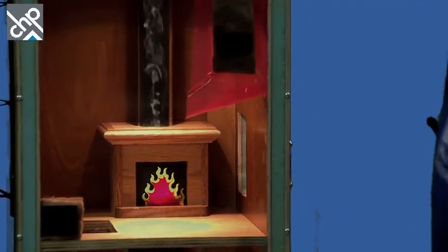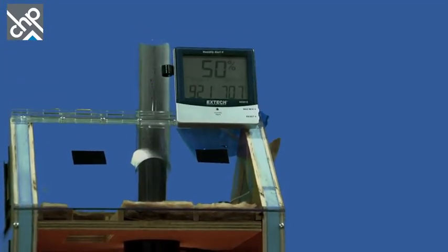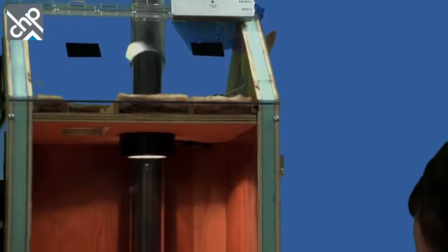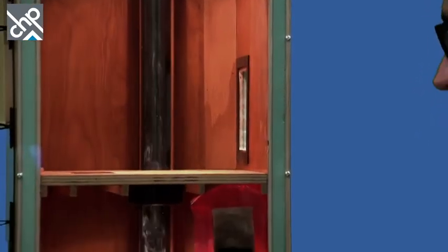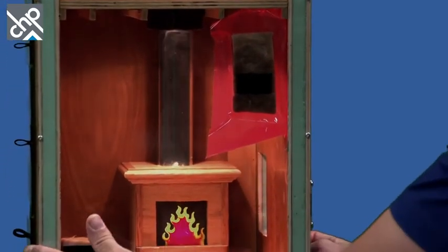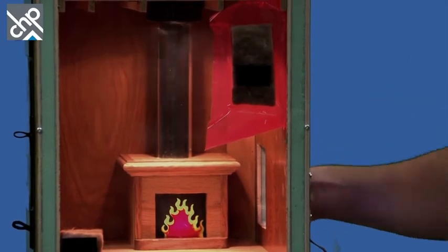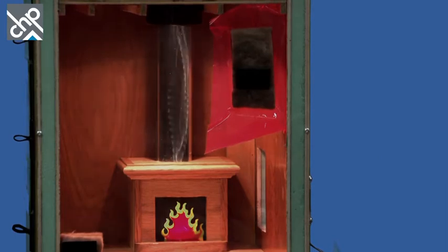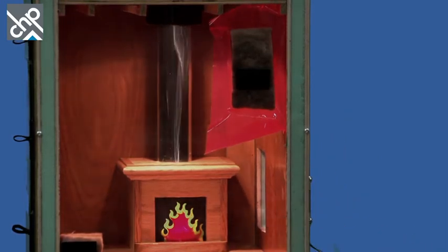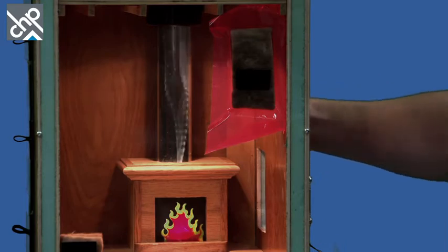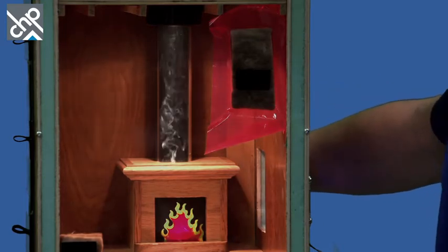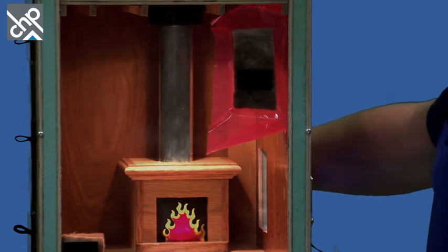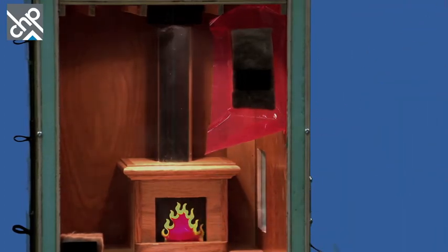So what we want to see is what happens when we've got an exhaust fan that's going to play with that. So I'm going to turn my exhaust fan on here on the lowest setting. Ooh. And immediately, what happened? Let's do an instant replay here. So I've just opened up some combustion air to the back of the fireplace. We see that the thing is drafting properly. Everything is working as intended. But with the exhaust fan, if I seal that combustion air up, it starts to slow. Dramatic backdrafting inside the house.